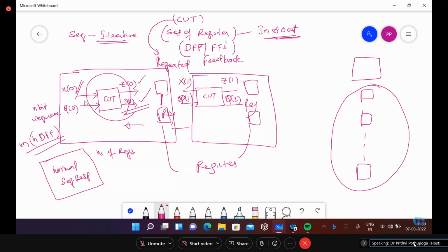When you want to test, this has to go to the next stages based on how many sequence inputs you have or how many segments of testing you need to do. So when you are testing, we give the sequence, find the response, store it on flip-flops, and send it to the next stage. If not, just give the input and find the output. These are the two operations, normal and testing operations, performed on each circuit. Every time, the user won't be testing now.